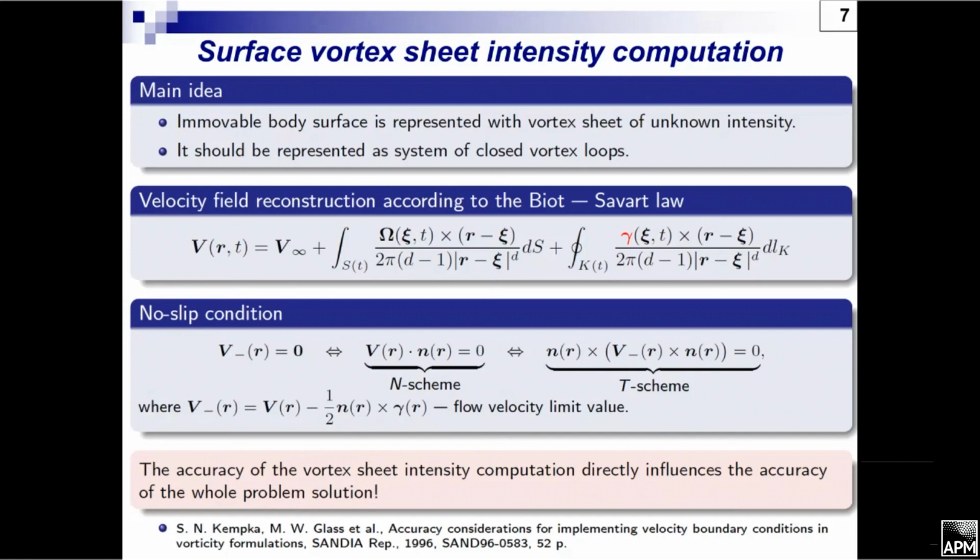The main assumption is the following: we use a kind of implicit scheme. We perform a time step, consider the vorticity generated during this time step to be distributed in a thin vortex sheet, and solve the problem implicitly, determining its intensity. So our scheme, in some sense, is a self-correcting scheme. And this is a very, very important feature.